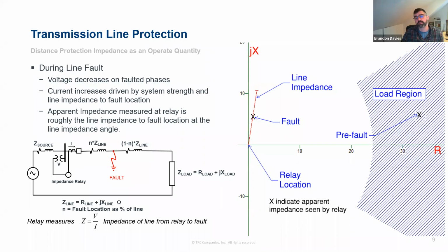Yeah, so fault impedance is definitely something that we need to think about as protection engineers. I didn't go into a lot of detail on fault impedance in this, but some of the references I mentioned will have that. Basically, if you have a fault impedance, something like that tree falling, or arc impedance, you're going to have a new impedance in this branch here.